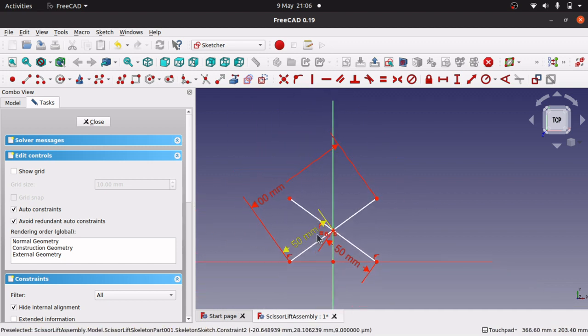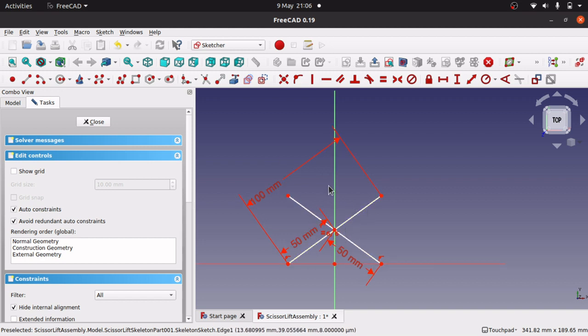And you see that this line is basically made up of a line, like so, and then I use a point on there. Now it's not often that I create a point on the sketch, but this is handy for connecting other items to it and stopping the topological naming issues. So let's create that point on there. See, it's a point on object constraint that's automatically constrained to there, and that means that we won't get the problem, or it should limit the problem anyway.